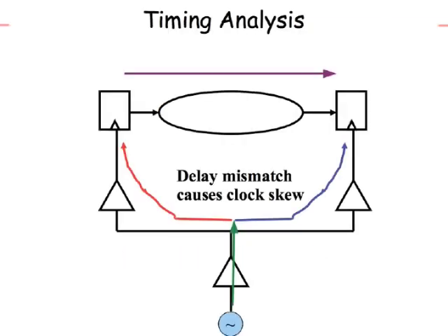So one of the things we considered last class was the impact of clock skew on the max and min constraints. Basically, it makes life harder. Whether it comes with a positive sign or a negative sign, the rule of thumb is you use the sign which makes your life harder as a designer. And really the problem comes because of the mismatch in delays of the clock edges.